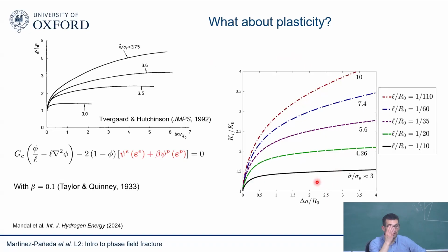And that also answers the other question that we were discussing before. What is the strength? What does fracture strength mean in an elastoplastic material, in a metal? Is it the grain boundary strength, or is it the UTS? Well, whatever it is, if you have experimental data, like that one, you could actually calibrate your L to fit that experimental data, because the only thing that changes here is the L. All the other parameters you know.